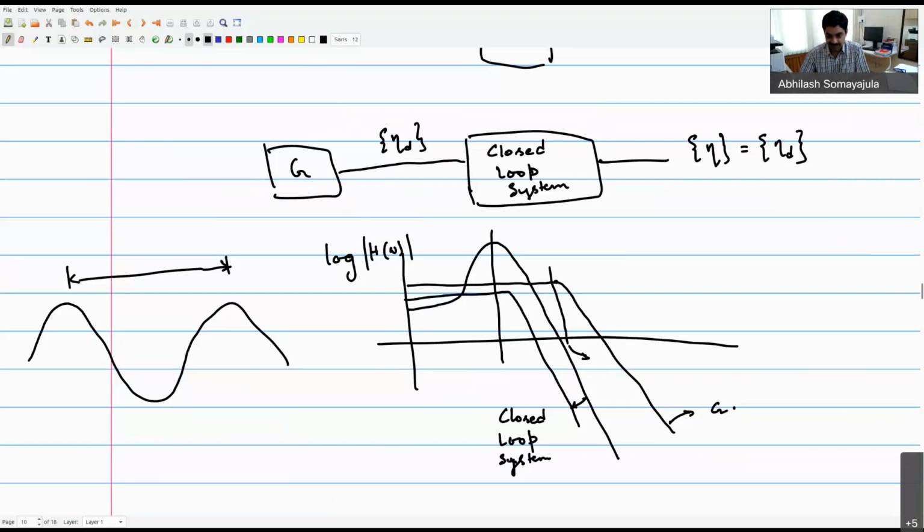Yes. The idea of the guidance system is what? It should generate a trajectory which can typically be followed by the craft. Yes. Right? So that has to ensure that the craft's bandwidth should always be more than the guidance system's bandwidth. Only then will the craft be able to follow whatever I'm asking it to track. Okay, I hope that point is now making sense.